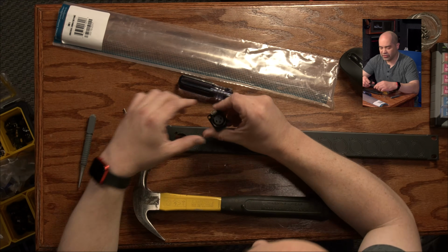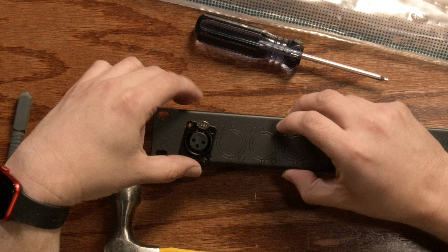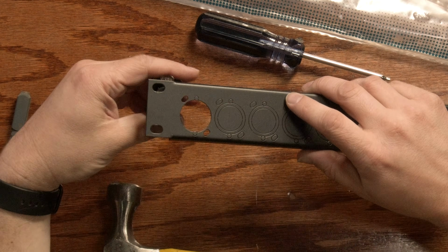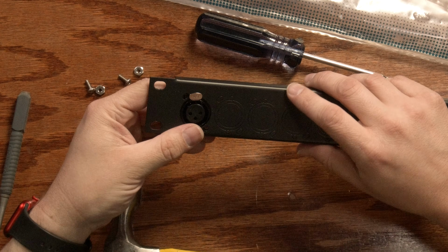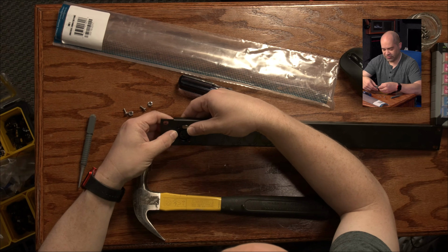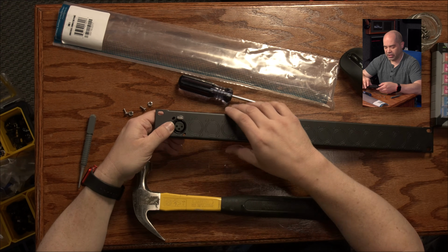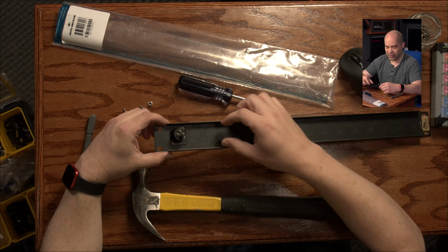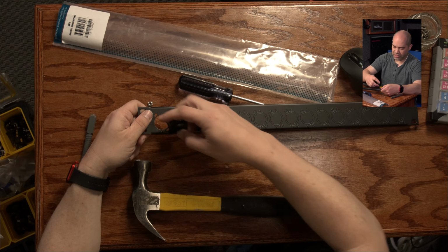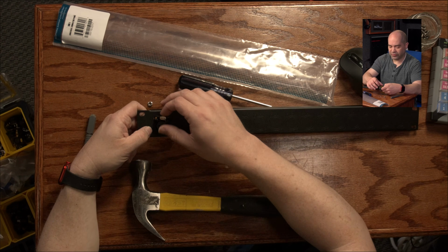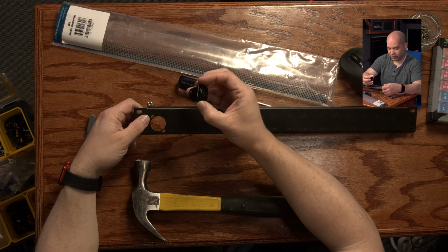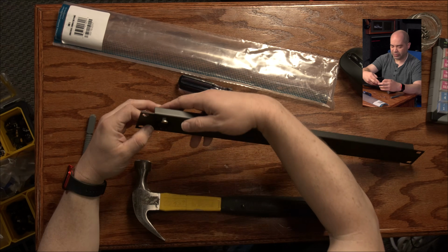Alright, and we actually have 2 different ways we can mount this. You can either front mount it, like this, or you can back mount it, and that looks like this. I prefer the back mount most of the time. I think it looks nicer, a little more professional than going with the front mount. And in addition, the other advantage you get by going back mount is you can leave the wires connected when you remove one, whereas if you go front mount, if you ever need to remove that, you're going to have to disconnect your wire. So if you're doing a solder connection like this, that can become a real pain. So again, I prefer back mount.